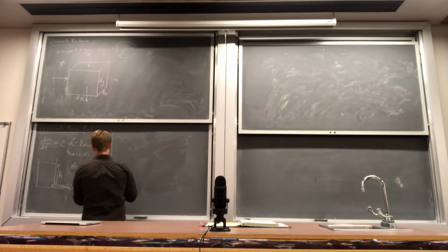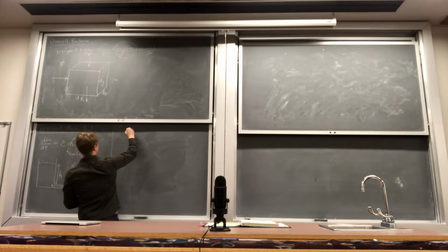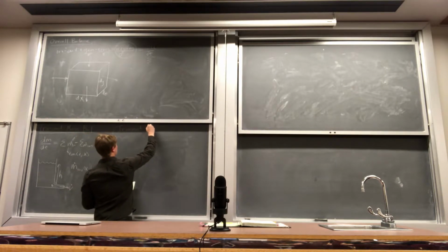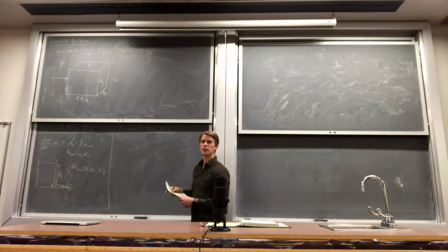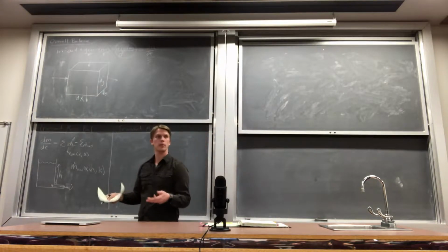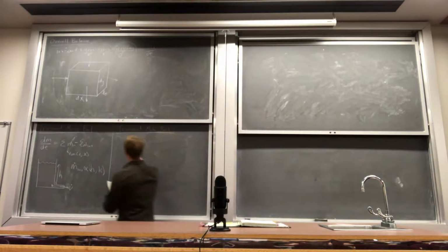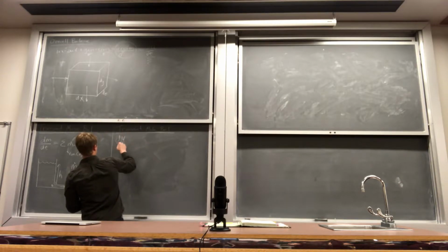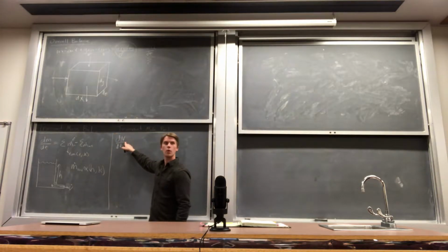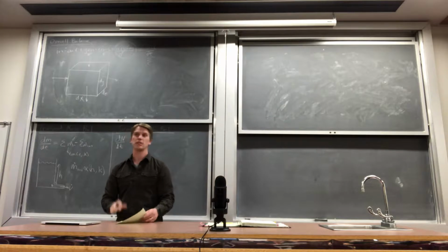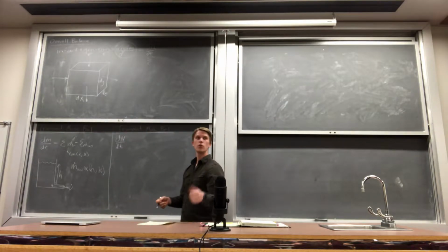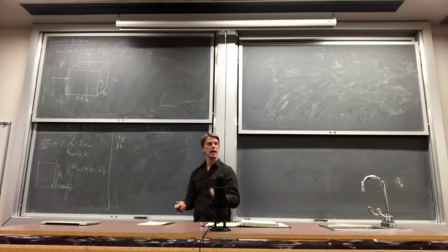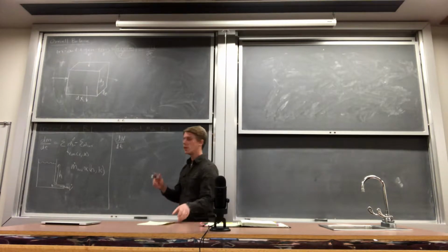Next, let's talk about mole balances. Now, in the mole balance, we cannot assume that the generation and consumption are equal to 0, because that's really what we care about when we commit to doing a mole balance. So we'll have dn/dt. Now, this could be the total number of moles, or this could be the number of moles of species i, right? We have the same rules and opportunities with steady state balances as we do with transient balances. You can do one for every species in the system, and you can also do the total balance. But again, degrees of freedom still hold true. One of those is going to be dependent on the others.